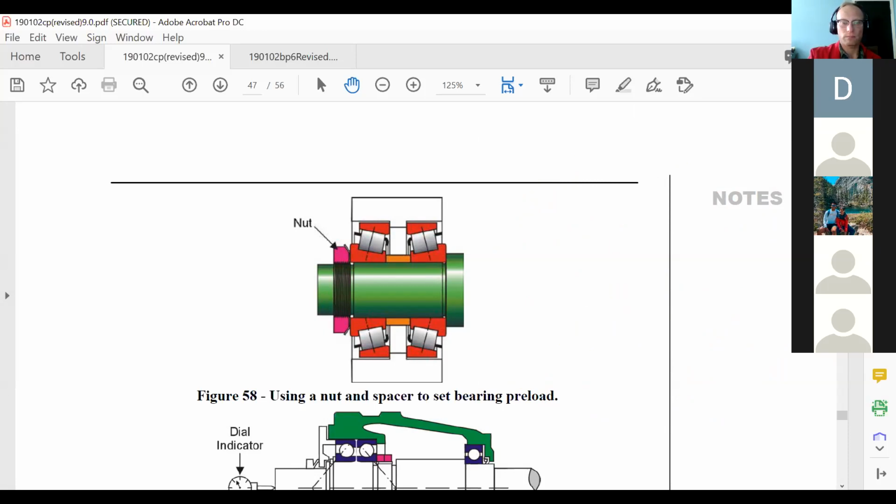So wouldn't the number that you get for making a turn matter based on the weight of the hub and stuff like that to make it turn? Would there be a value that you have? So there actually is. That's a good point. When you're setting these, they actually sometimes give you different values if you have the drum on the hub or the wheels on the hub still, or if it's just the bare hub. But when you're measuring this preload, they know everything.